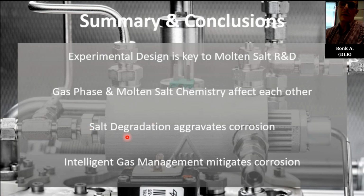I could demonstrate that salt degradation leads to corrosion. You've seen that at these high temperatures. You've seen it by the SEM images I've shown you before. But also that there is a chance for us, because whenever people talk about corrosion, there's also a chance for us to mitigate corrosion by thinking about intelligent gas management techniques. And this is the key to the next generation CSP or in general energy storage systems.